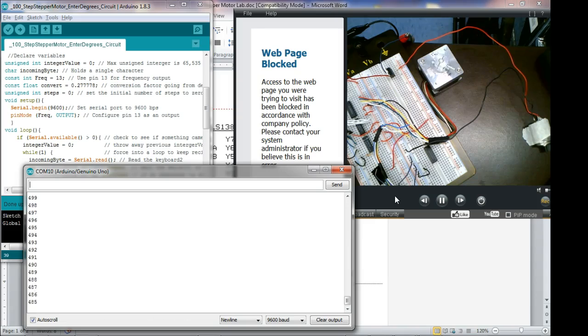This is called a stepping motor. And you can see what's really neat about these. We can run these things open loop. There's no feedback from it that tells me that it's at 360 degrees. What it does is it's got steps. It's 100 steps. If I tell it to step 100 times, it would go what? It would go 360 degrees. If I tell it to step 50 times, it would go what? It would go 180. All I've done is come up with what we call a transfer function that does a little math that translates degrees into what? Into steps.